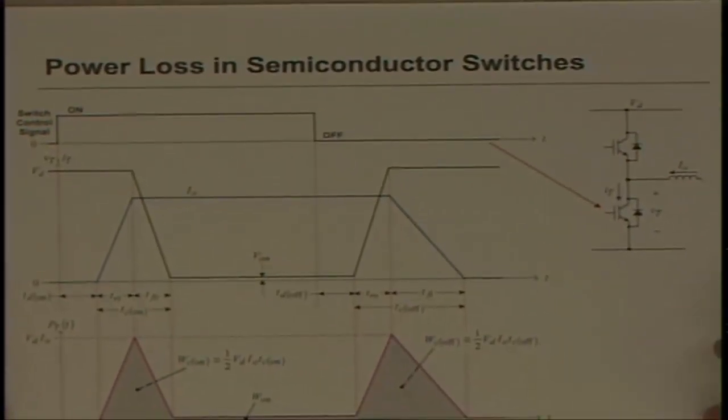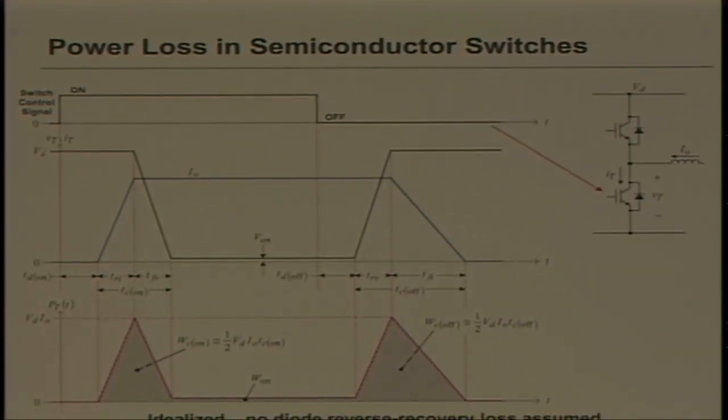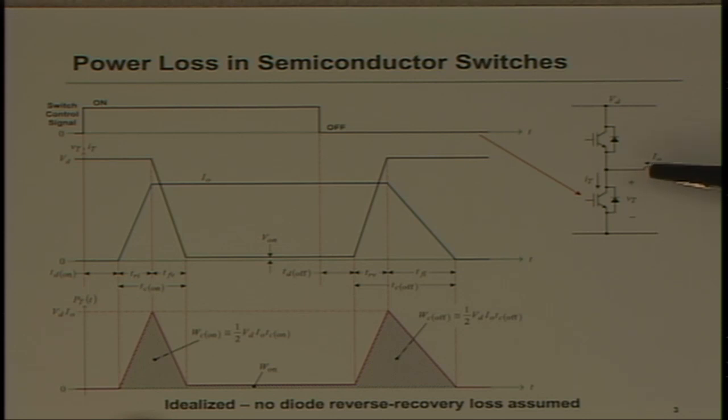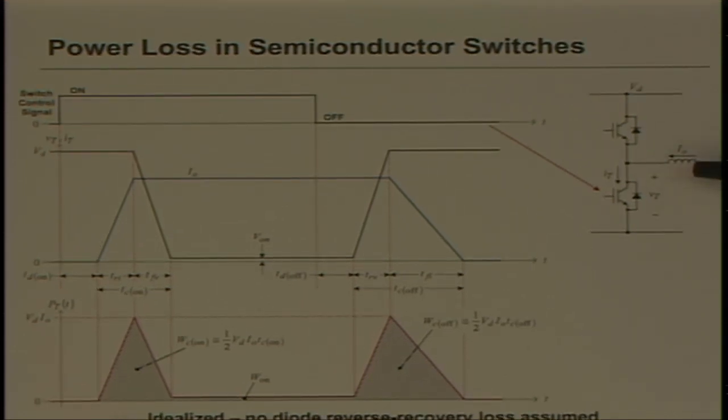So before I go too much further, I want to just cover switching in general. I know you've probably seen this all before, but there's a couple of key points I'd like to make on driving, whether it's a FET or an IGBT, but this is an IGBT example. Very commonly, when you're dealing with power electronics, you have an inductive load, right? So this could be part of a converter, could be the magnetizing inductance of the transformer, output filter, or whatever. And the characteristic here is that during the short switching interval, the inductor behaves like a current source. So when you're switching, I know Ned's probably explained the concept that you have a voltage port on this side, and you have a current port on this side. So you're switching voltage here, driving current in this load.